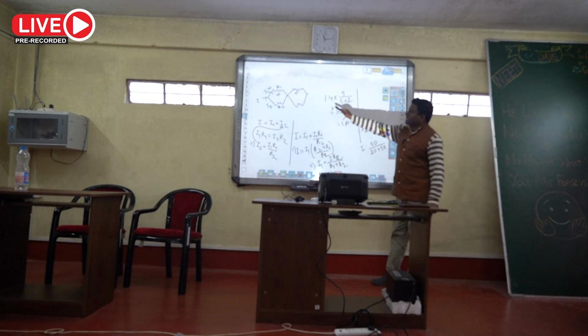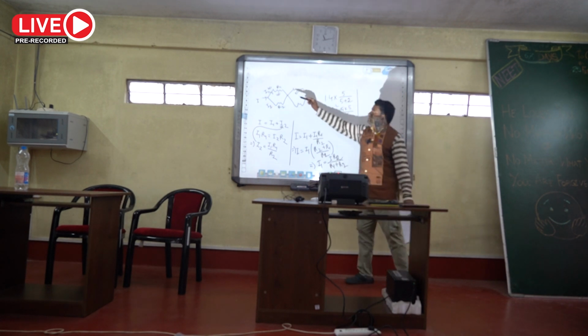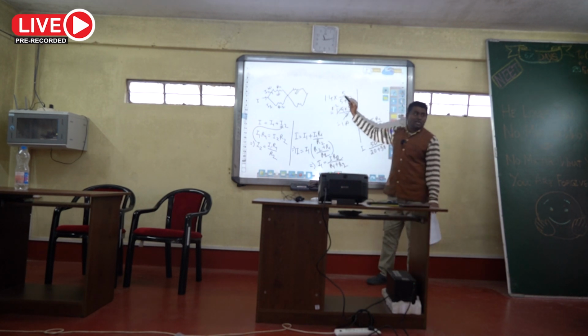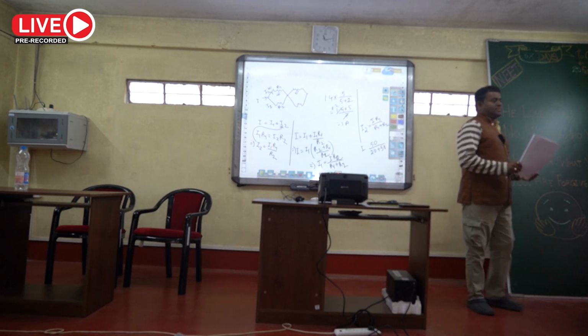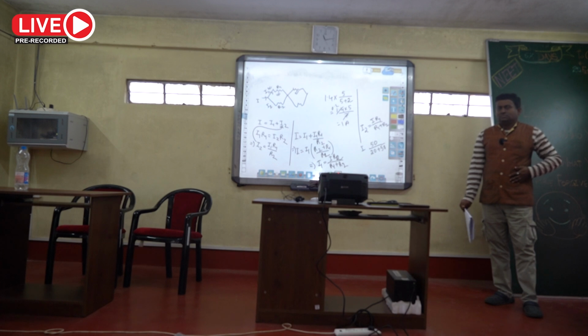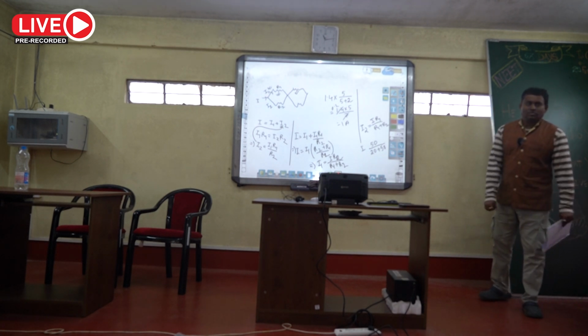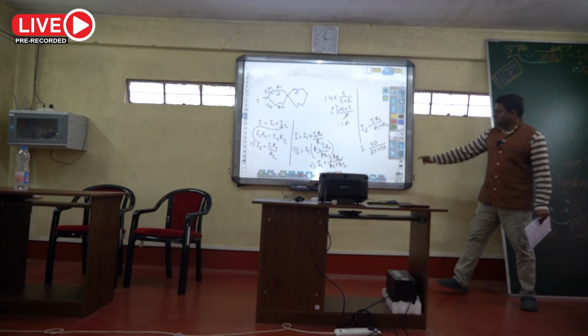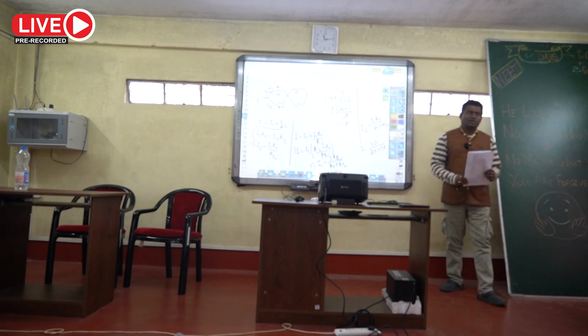Means total current into, current through which resistance is required? R1. So I will write here the other resistance divided by sum of the resistance. Because otherwise in the exam there is not that much time to derive all these formulas and then solve. Whenever in the parallel combination current splits, you can use these two formulas directly to find the current through two resistors which are in parallel.